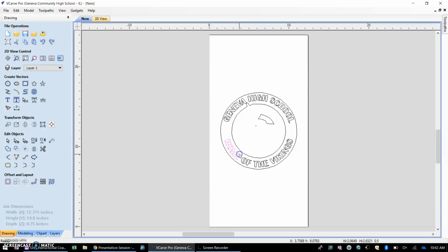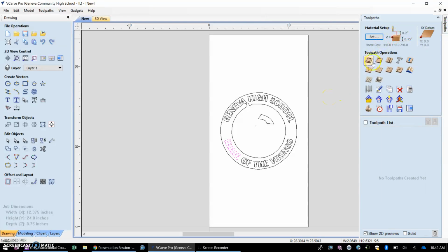And in general, when you create it for text and you want to cut for text, when you go to the toolbars menu in the top right, you want to use the VCarve setting. The VCarve setting uses a bit with a cross section that's a triangle. The bit actually cuts like it's a cone, right? And it goes in and out, and it automatically changes the depth of the cut so that it can go back to the corners and get sharp corners on the image itself.